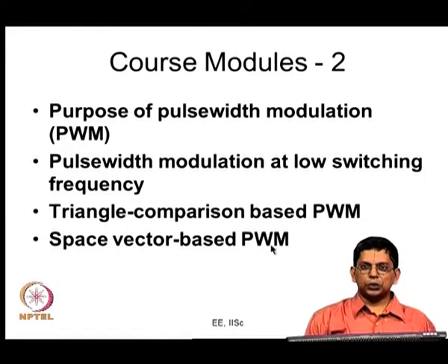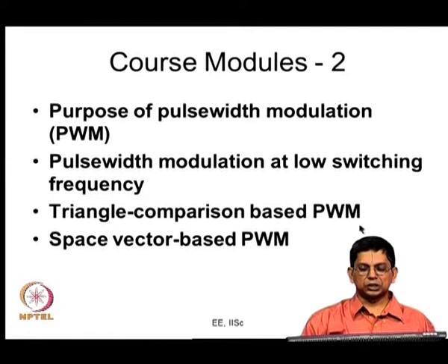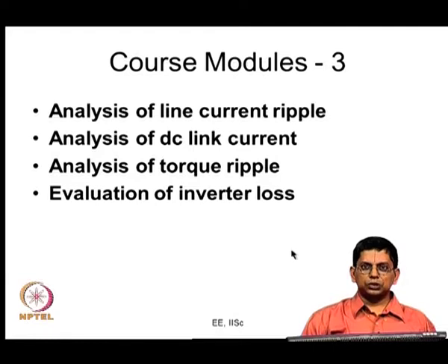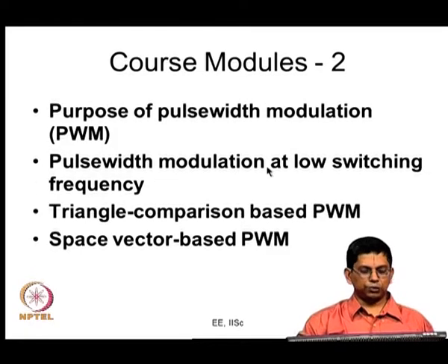You can have continuous PWM methods or bus clamping PWM methods implemented through either approach, but there are certain advanced bus clamping PWM methods which are space vector methods, as we have observed on numerous occasions before. Thus, we regard space vector based PWM to be more general than the triangle comparison PWM. Now, this is all done in the context of 2-level inverters, like the entire PWM generation.